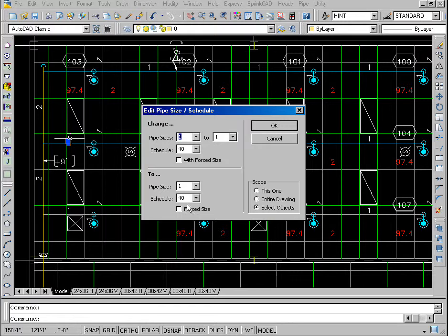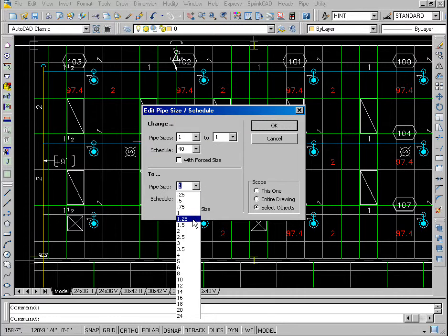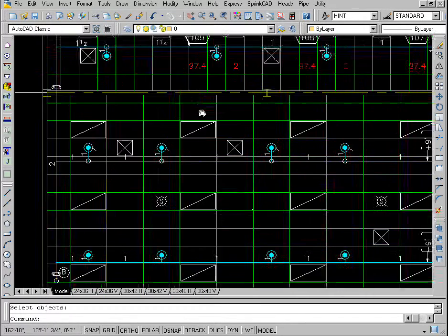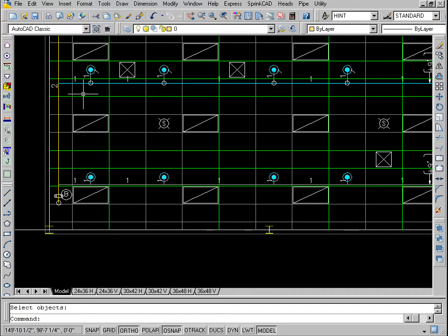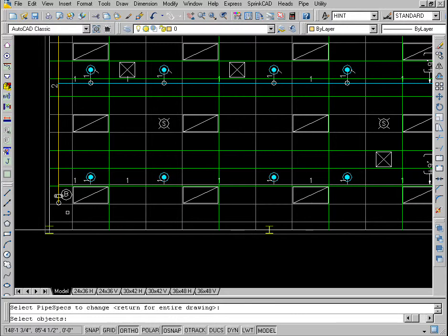Double-click on the pipe sizes closest to the main and change the sizes from 1 inch to 1.5 inches. There are 3 sizes to change. Also change the next pipes to 1.25 inches. In the lower office room, change the third branch pipes from the end to 1.25 inches and the fourth and fifth to 1.5 inches as shown.